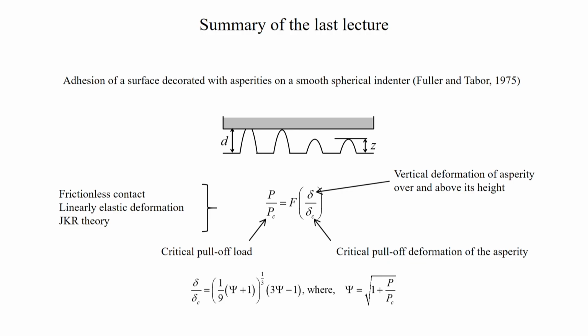And this particular observation was attempted to be explained by considering that the surface consists of this kind of asperities. The asperity heights vary according to a given functional form, and although the height varies, they have the same radius of curvature at the tip. So, this looks spherical there. And now this adherent, which is a smooth rigid adherent, is being brought in contact with this adhesive having asperities. So, first the asperities contact, and now you apply more load and then you pull it off.